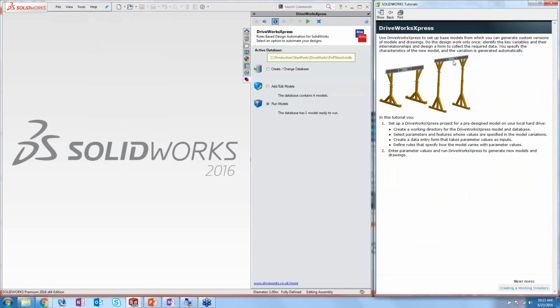So would you recommend people at least start using start parts or template files on their parts and assemblies, or they could jump right into DriveWorksXpress? I think people should do both. Certainly for a block, there's probably not a big payback to putting that in DriveWorksXpress. Now, certainly the drawing was kind of cool, and I could argue that it'll be a little bit faster, but you can't be simply going to a part, save as a part, and using it over and over again. Yeah. It's fast. If you want to start putting more into it, the more complex your start parts get, then I think you probably ought to be looking at using DriveWorksXpress as your start part tool. Got it. Yep, that makes a lot of sense.